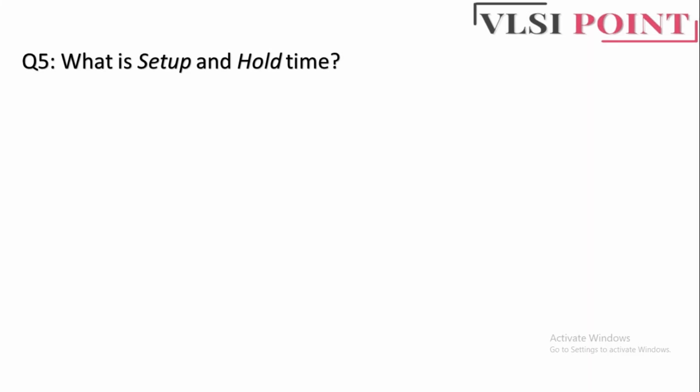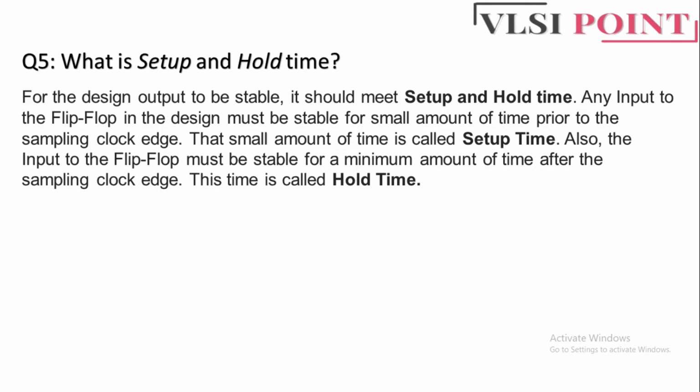Coming to the next question, what are setup and hold time? This is a very important question of STA, and these STA questions will definitely be asked in your interviews. So setup time and hold time are the timing constraints in digital circuits that are important for ensuring the correct operation of synchronous sequential circuits, such as flip-flops, registers, and other memory elements. The setup time refers to the minimum amount of time that the signal must be stable and valid before the clock signal arrives.